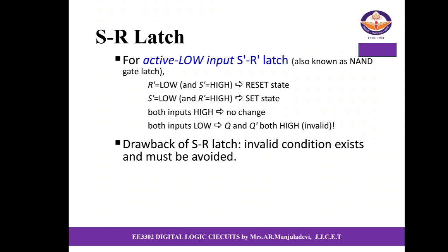For the active low input S dash R dash latch, it is also known as the NAND gate latch. When R dash is low and S dash is high, it is said to be reset state. When S dash is low and R dash is high, it is said to be set state. When both inputs are high, there is no change. And when both inputs are low, both outputs are high. It is said to be invalid. Drawbacks of SR latch: the invalid condition exists and thus must be avoided.